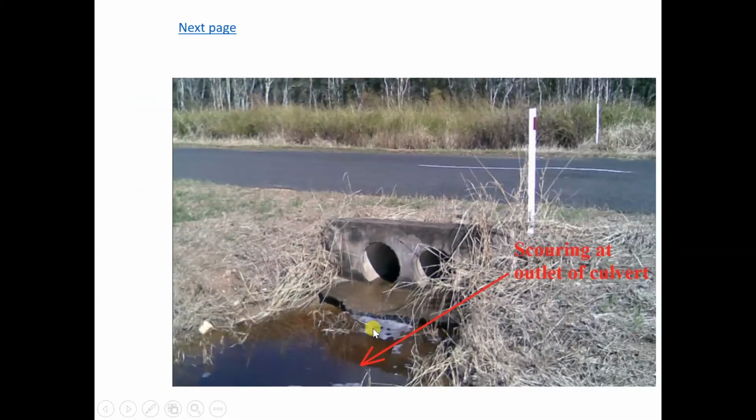So for example, if you don't protect it properly, the river is obviously flowing from the right hand side to the left on this picture. If the water is flowing very fast, it could create a pond at the outlet end. So we need to protect it properly. Sometimes we use riprap, big boulders or rocks, at the exit end, to make sure that the water exiting from the culverts will not erode the outlet.